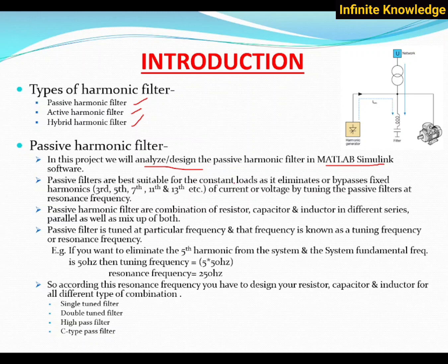and if you are checking the harmonics, the harmonic study is a major topic in which some vendor comes to your industry and checks the level of harmonics by putting in some instrument like a Fluke. Fluke is a harmonic analyzer. Fluke is a company that creates different measuring instruments.